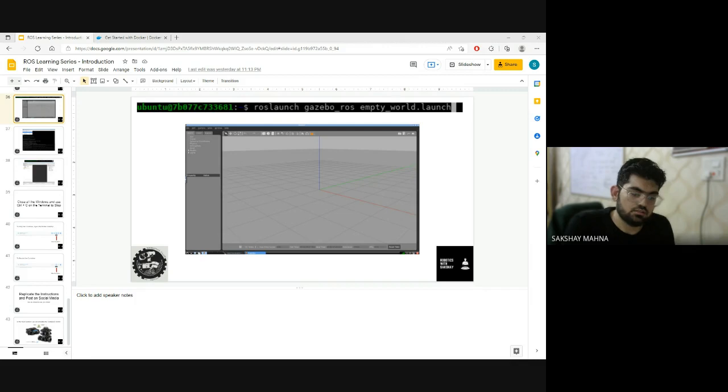I have installed ROS2 Galactic on Ubuntu. I was not able to replicate ROS launch. Okay. So Arnav asks, sir, I have installed ROS2 Galactic on Ubuntu and I was not able to replicate ROS launch, ROS run, which you demonstrated. Now for ROS2, the commands are different. For instance, over here, for ROS launch, the command is ROS2 space launch. Now there is a slight conventional difference between how we call the different commands in ROS1 and ROS2.